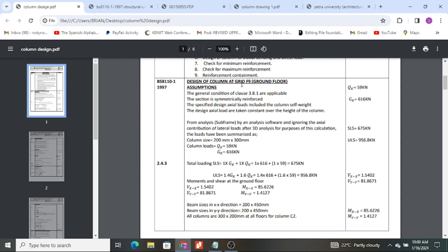It's very important for you to label so that we know the location of your column, and we can counter-check it with the drawing you provide, so that we are able to identify the column and carry out checks to find out whether your work is okay. So labeling of your column is very key. Don't just design a column that we cannot see where it is when you give us your drawing.